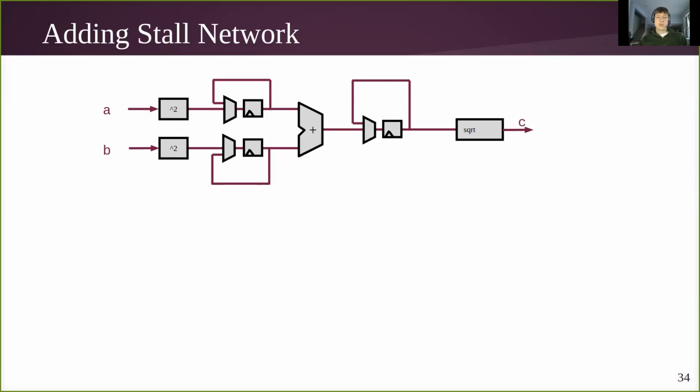Logic synthesis tools are able to easily transition from one implementation to the other. It doesn't really matter how we represent these in our model. In a transaction level Verilog mindset, I prefer to think of these as recirculations. And then we need to add our stall signal, which controls the recirculation.